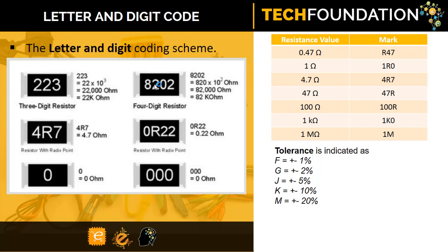For instance, if a resistor is expected to drop about 10 volts and allow a current of about 1 amp to pass, then the wattage according to the P equals IV formula would be 10 watts. So choosing a 20 watt resistor will be the best thing to do. If the size will matter, then try using something like a 15 watt, or at best split it into a number of parallel resistors. We shall look at this again when we get into circuit design, because it is a very, very important concept.